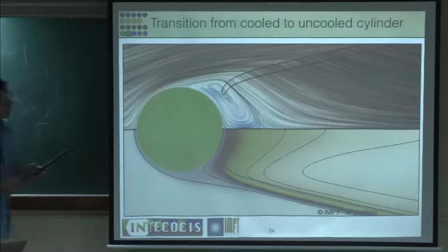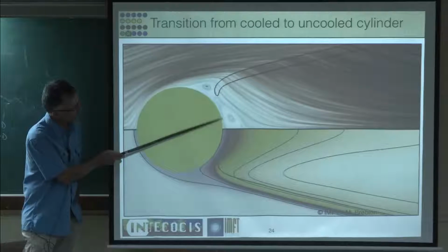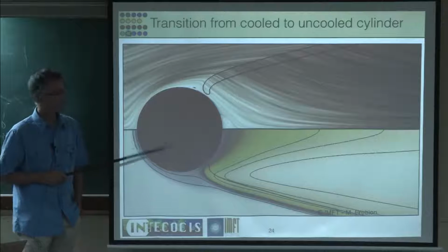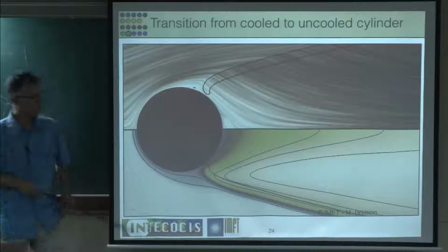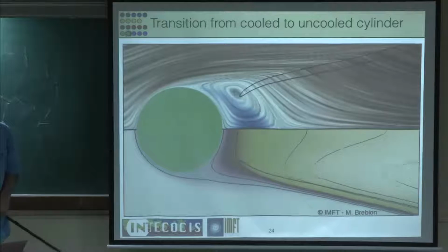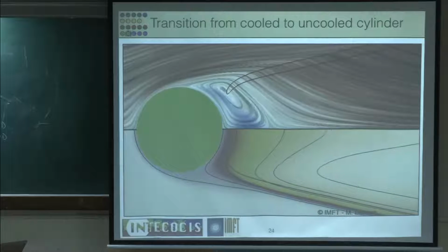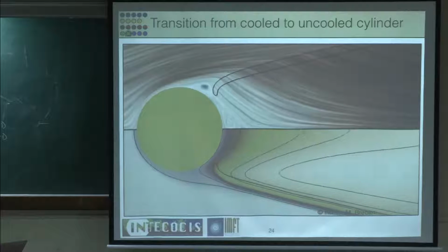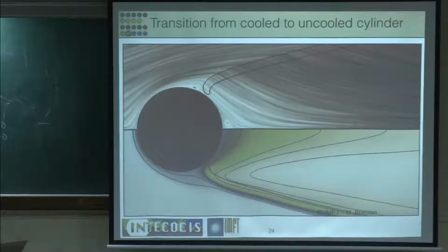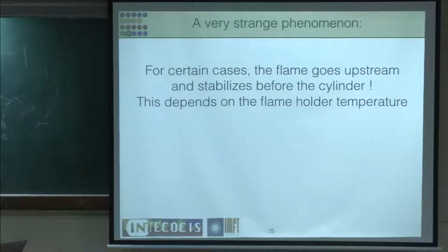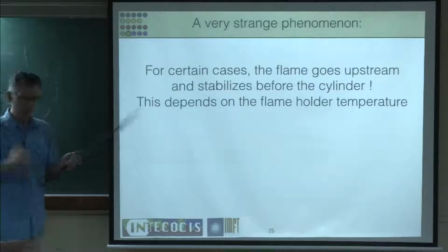So the flame moves slowly, slowly back, and the recirculation zones go away. And then we end up with this flame, where now there's only 2 recirculation zones. And you can see that there's really not much in common between these 2 states. So you have to account for heat losses when you do this kind of thing. Okay, now it's finished, and now it's another stable point, which really means that we need to account for these things. Now, just to finish, what about radiation?